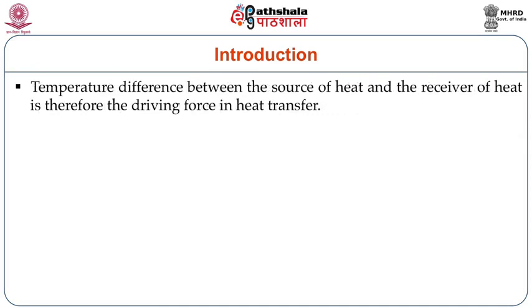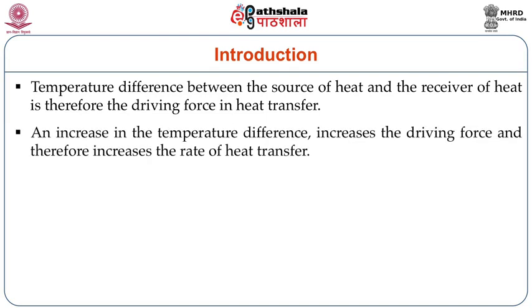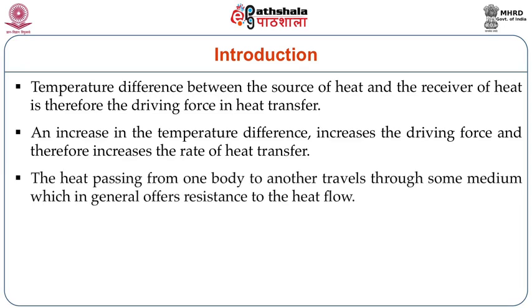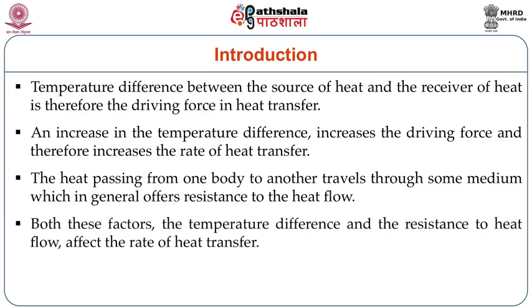Now, the temperature difference between the source of heat and the receiver of the heat is therefore the driving force in the heat transfer at any time. An increase in the temperature difference increases the driving force and therefore increases the rate of heat transfer also. The heat passing from one body to another travels through some medium which in general offers resistance to the heat flow. Both these factors, that is the temperature difference and the resistance to heat flow, affect the rate of heat transfer.